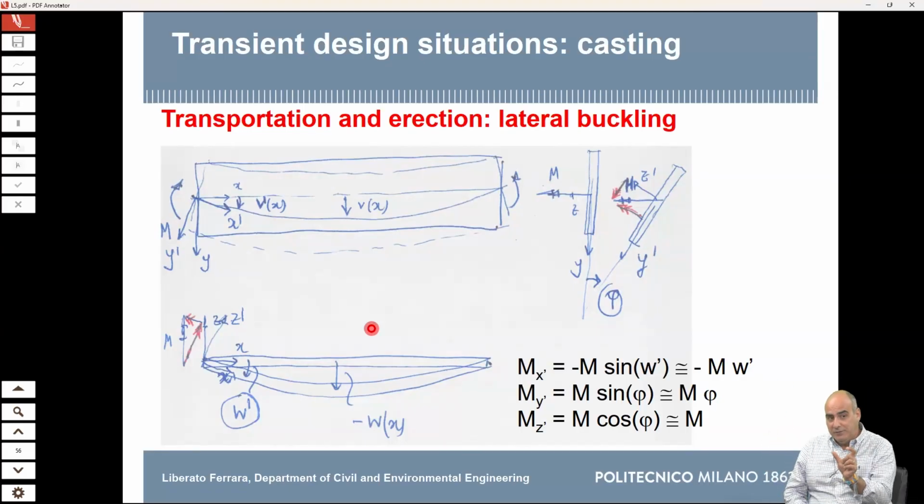But the other part of that assumption is that we say the deformations and the displacements are small and negligible. The second part is the most important one, because the fact that they are negligible means that whenever we work out our models, we do not consider the beam or the column or the elements deformed. We simply work with them as rigid and undeformed. When you have a beam and you calculate the vertical support reactions, you don't consider that the beam sags, you consider it straight. That is the most important part.